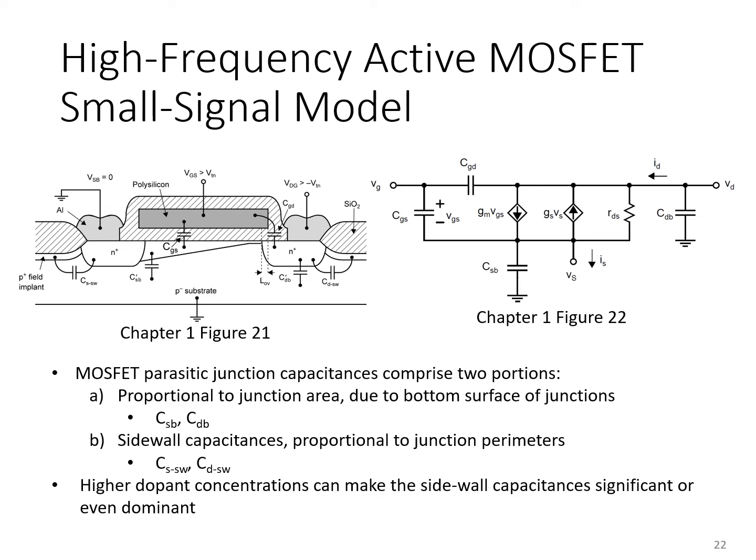Now, the capacitances that are focused on in this picture here are the ones that arise because of oxides, like silicon dioxide, separating two conductors, and also those that arise because of depletion layers that are formed across reverse biased PN junctions. But especially in very short channel length MOSFETs, the picture is even more complicated than this.